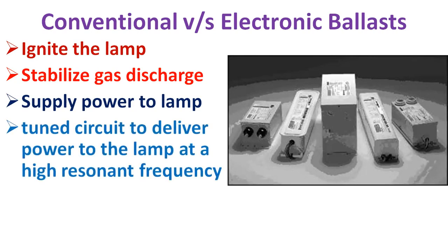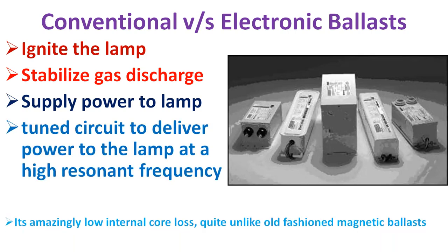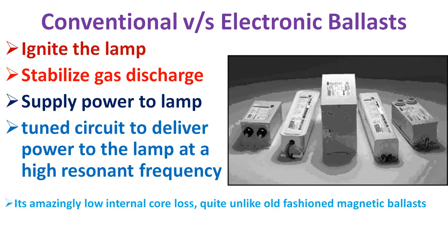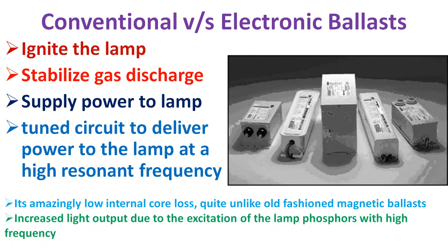On account of the mechanical switch, which is a starter, and the low resistance of the filament when cold, the uncontrolled filament current generally tends to go beyond the limits specified by Indian standard specifications. With high values of current and flux densities, the operational losses and temperature rise are on the higher side in the conventional choke.